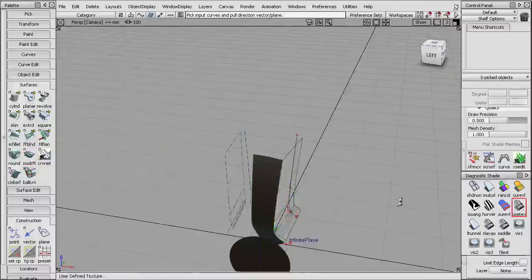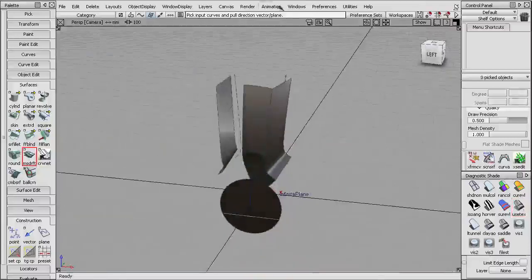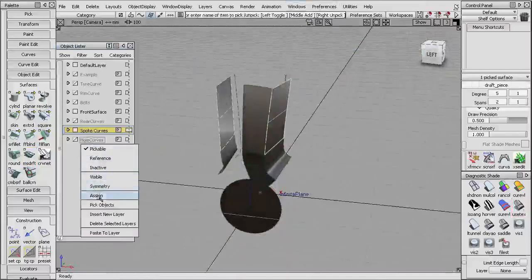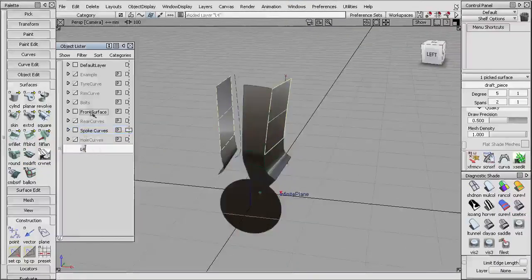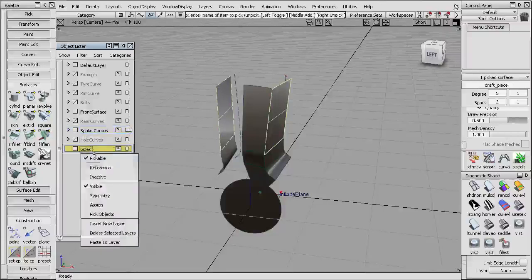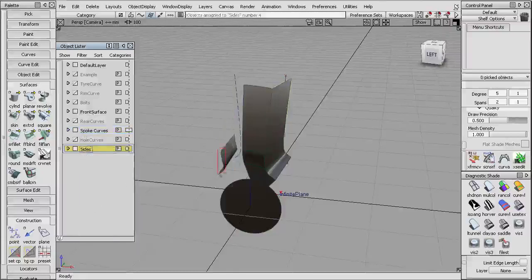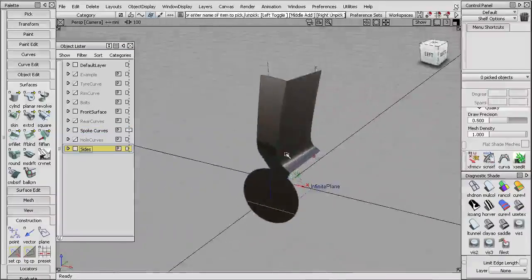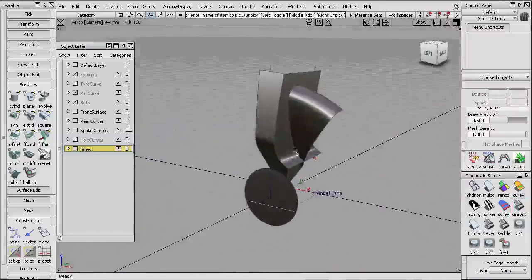Now I've got quite heavy surfaces here because of building from a trimmed edge, but this is my first design iteration, so I'll live with that for now. And I'll tidy up my surfaces onto a layer, and then all that's left to do is intersect with the rear surfaces and the rim. So in the next section we'll look at finishing that off with some G2 curvature fillets.